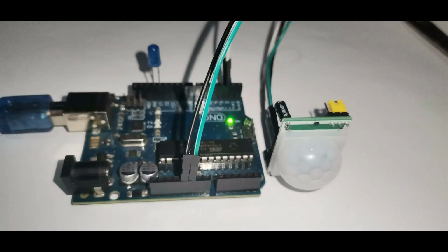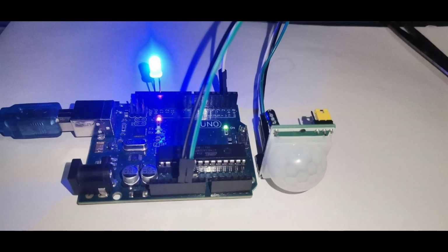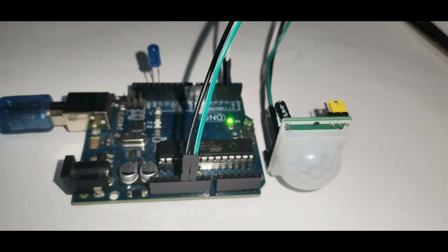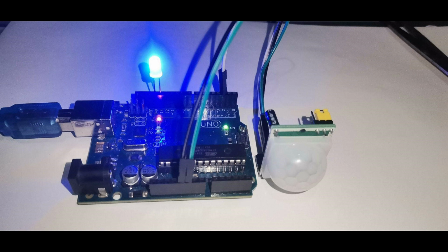Wiring wizardry, connecting to the invisible. Follow the wiring diagram. Ensure you have the correct one to create the following connections: PIR sensor's output pin to a digital input pin specified in the code. LED's anode to digital pin 30, cathode to ground via resistor.